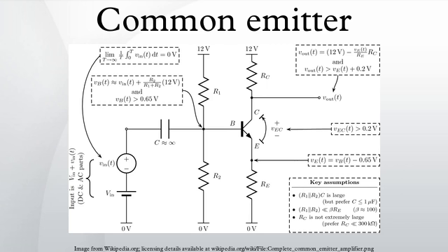Radio. Common emitter amplifiers are also used in radio frequency circuits, for example to amplify faint signals received by an antenna. In this case it is common to replace the load resistor with a tuned circuit. This may be done to limit the bandwidth to a narrow band centered around the intended operating frequency. More importantly, it also allows the circuit to operate at higher frequencies as the tuned circuit can be used to resonate any inter-electrode and stray capacitances, which normally limit the frequency response. Common emitters are also commonly used as low-noise amplifiers.